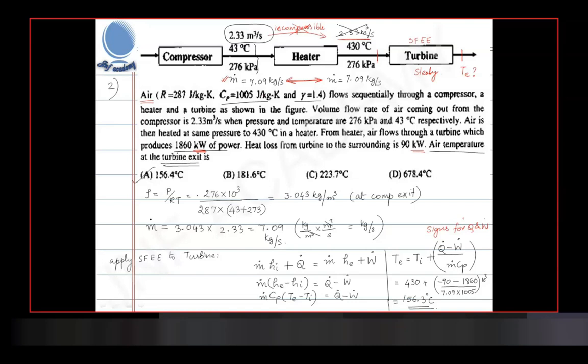That's a good question. In fact, for your gas turbine cycle, your Brayton cycle that we will analyze, we are going to assume that the turbine is going to run the compressor. A portion of the turbine work goes for the compressor. We are going to make that assumption when we do cycle analysis. And when it comes to jet engines, that will be a major assumption for us. For a jet engine, it's not like the land-based gas turbine engine, which is required to produce work.